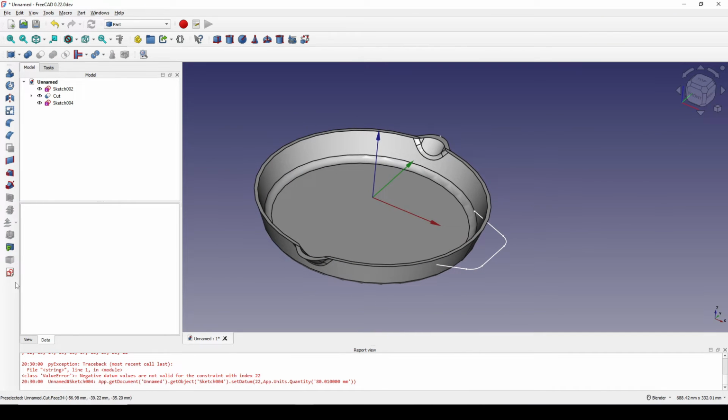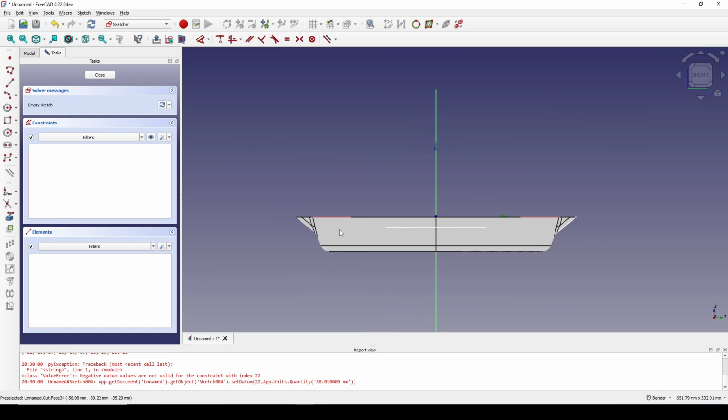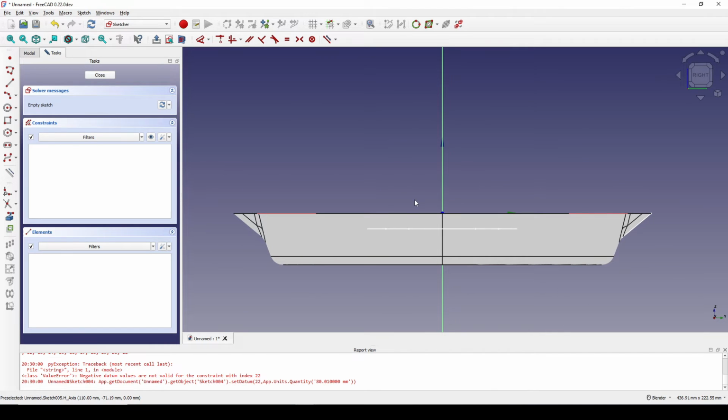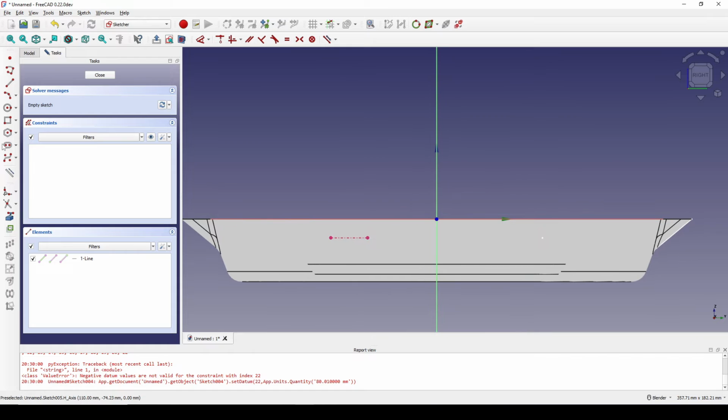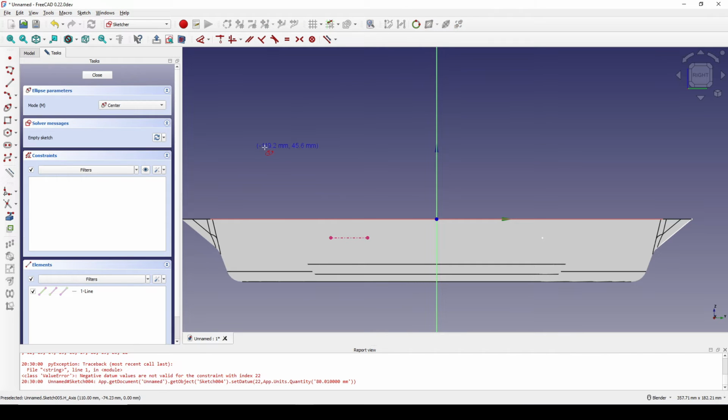Next I create a new sketch in the right and offset it to 110. I will reference this line on the right, and I view the section. I create an ellipse. I drop the circle down and create an ellipse by center.